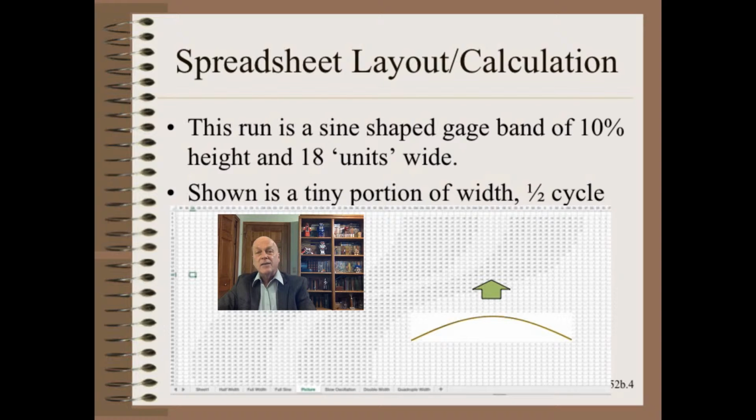Similarly, the oscillation is also non-dimensionalized. It has no less than 18 rows and has many more for wider oscillation. The technique shown here is quite simple and quite adaptable. The user is completely free to make a finer mesh if they desire. The user is completely free to make any shape of profile and oscillation that they wish. Indeed, I modeled the slitter lip as an exponential shape.